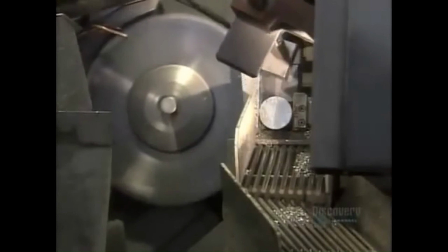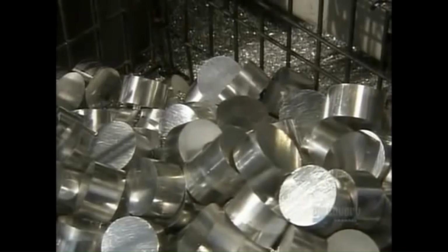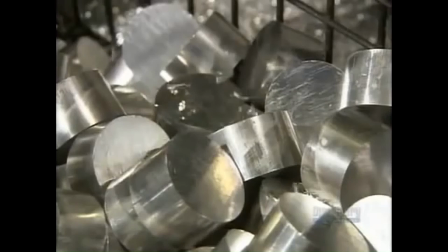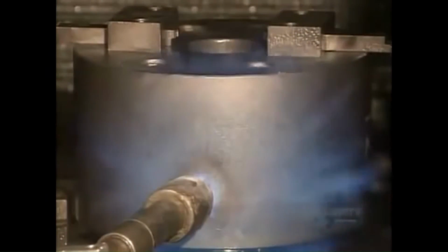For pistons, it is recommended to heat the forgings twice more. The first to strengthen the metal, and the second time at a much lower temperature to stabilize the internal structure of the piece. Machining is also required. The forging force is calculated using the same formula that was used in the previous part.